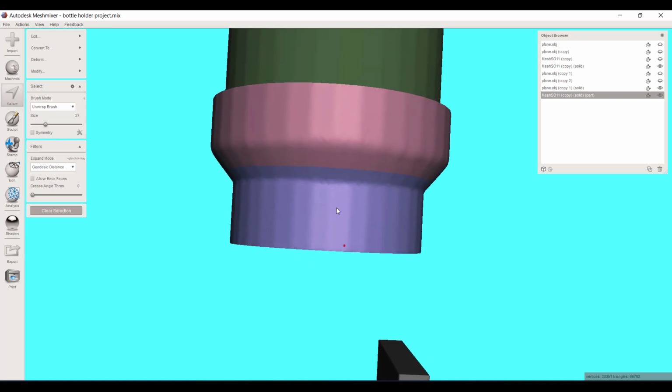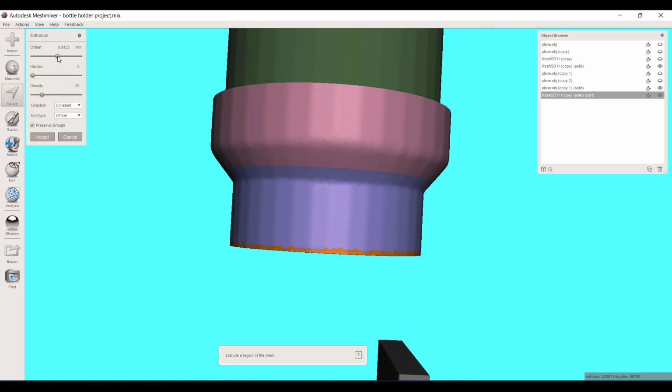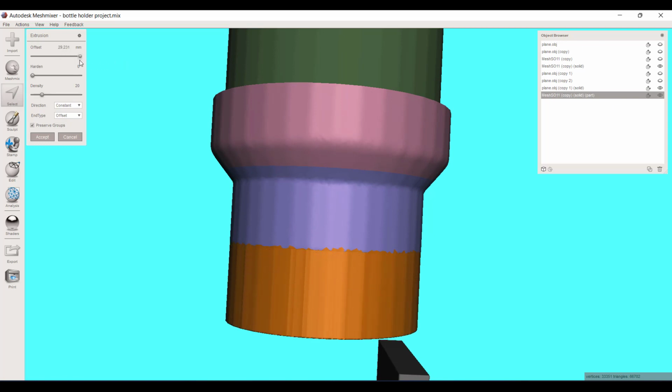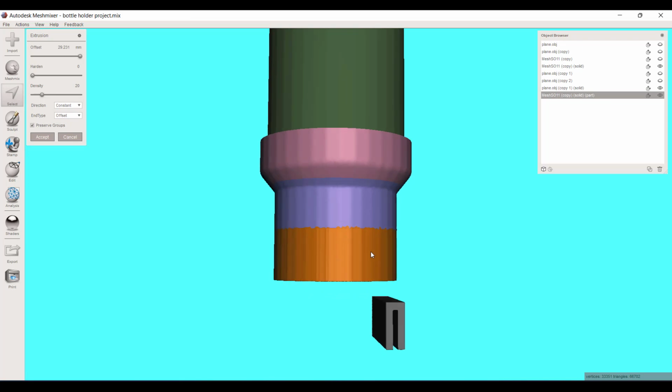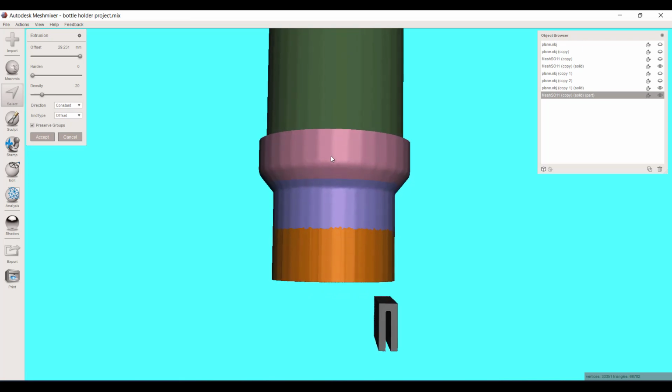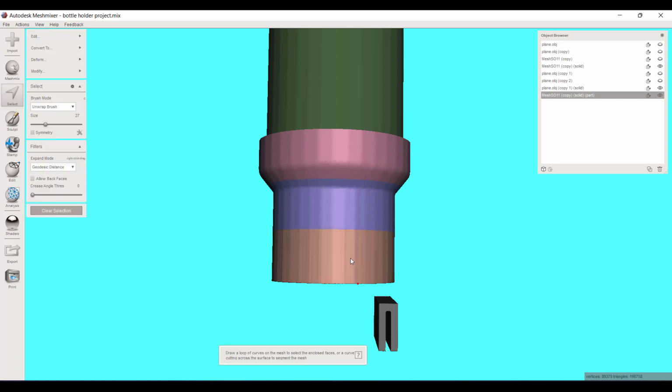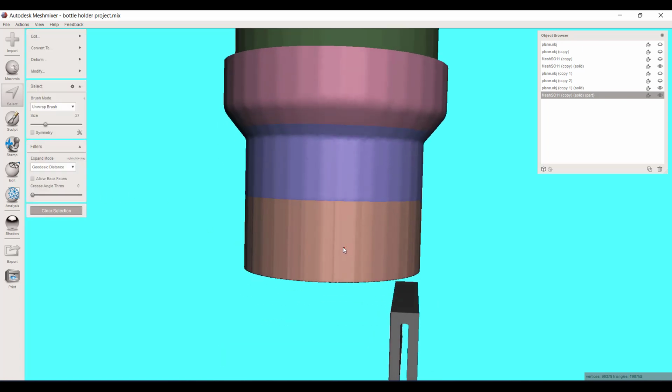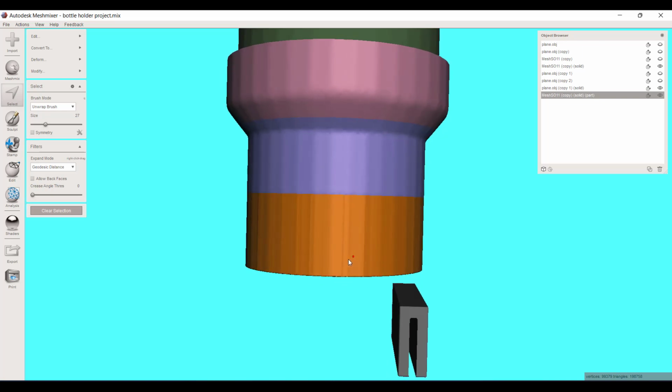So instead, I'm going to just go to D for extrude, and I'm going to extrude a big chunk off of this. Once again, because I'm in the worldwide frame, my extrusion happens directly down in the Z dimension or whatever that is. All right, doesn't matter really the distance, but I'll just put in an even number. All right, that's useful that it's just made this into a new face group. Now watch what happens here. Once again, if I go to soft transform, what soft transform does is it transforms it, but it blends it. It makes it nice, smooth transitions.